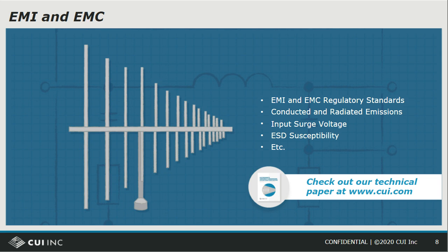On an external supply, it is quite often the case that radiated emissions turn out to be an issue. It is an issue, but it is well known and it is easy to deal with, and that is that what are referred to as lossy ferrite beads are put on the DC output cable, and this absorbs the energy coming from the load and does not allow the DC output cable to act as a very efficient antenna.